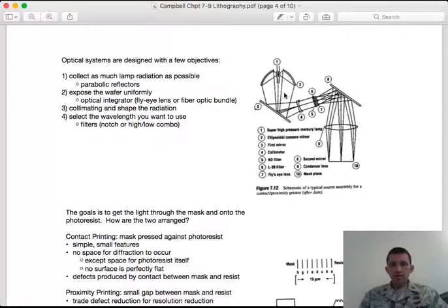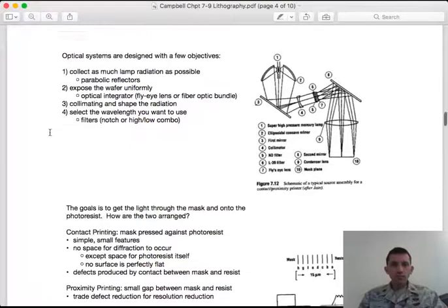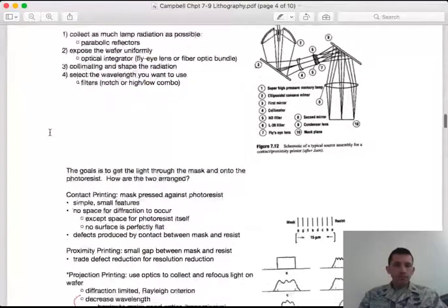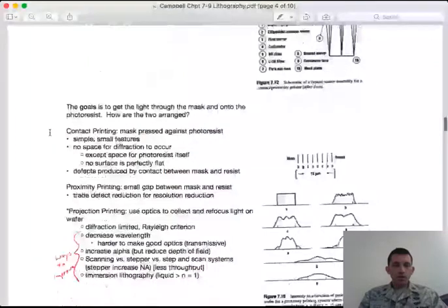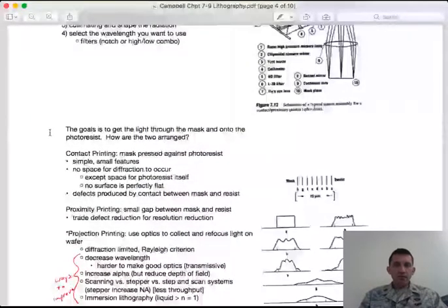Remember that the light is emitted in all directions, so I have a parabolic reflector to capture that light, and then, say, a collimating lens, a fisheye lens to create greater uniformity, and then on various mirrors and lenses to eventually collect and focus the light collimated and uniform across the surface of my wafer. Or at least to the mask.